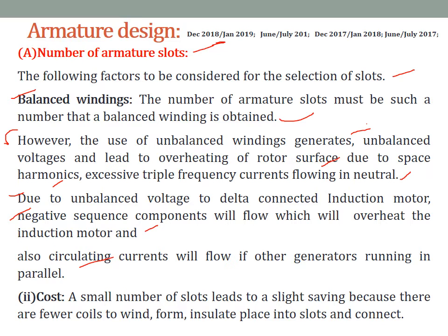These are the disadvantages. That is the reason you should always select the number of slots so that you get a balanced winding. This is an important factor.